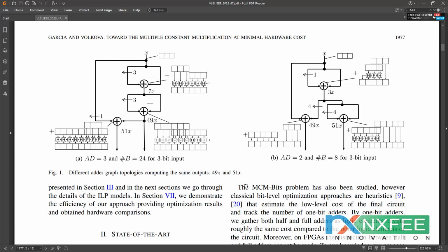For example, if we use a shift and addition based constant multiplication, we do not need a 16-bit addition in the final stage. We can use an 8-bit addition, and the internal architecture of this process also gives better results. Here, figure 1 shows examples of the multiplications.